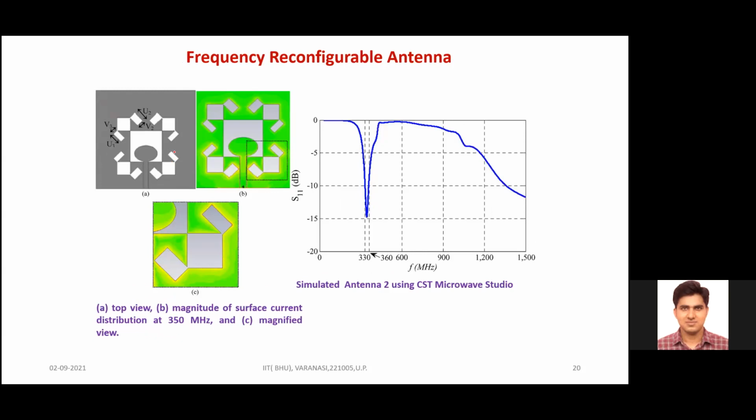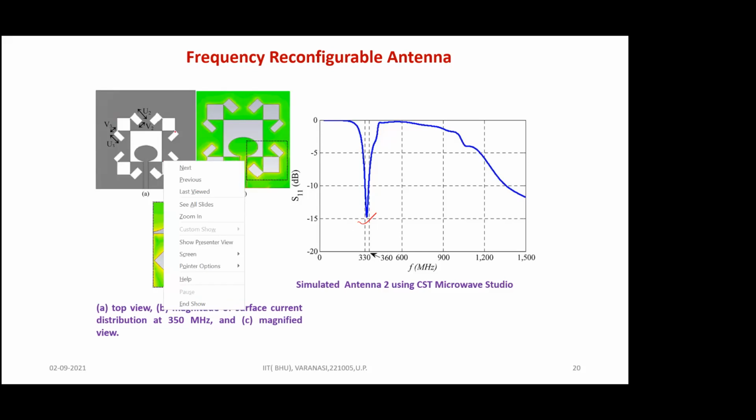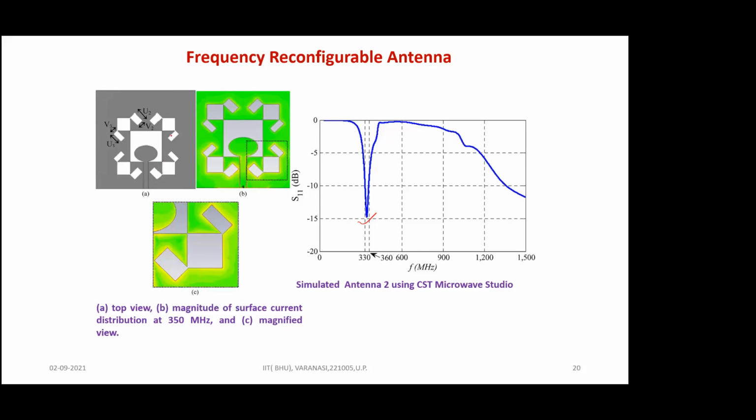Once we change the direction of this slot, you can go in a different direction and your polarization will change. Nothing else will change, but the pattern will change. Initially, he is looking for the frequency change. Now, putting the diode in a particular place needs connections. There is a connection only here, so we have to connect. This is the interconnect. So the number of PIN diodes, MEMS switches or varactor diodes has to be selected accordingly, depending on which direction the current has to flow. So you can choose.